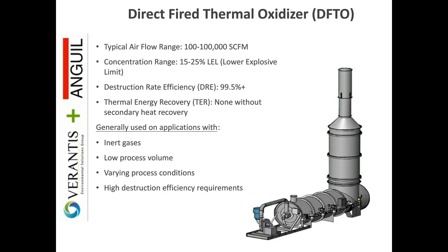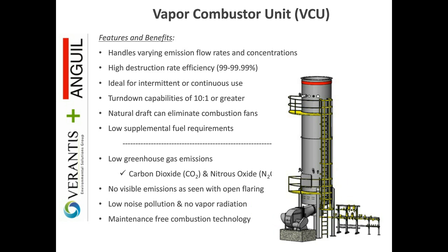And on the next slide here, the same thing applies to the vapor combustor. Really, the applications for the two are very similar. The vapor combustor tends to be applied more to the oil and gas industry. They're much more common in there. Also, you'll see these applied very commonly to tank farms where we're treating just tank vents, or say barge loading or truck loading or rail car loading applications.